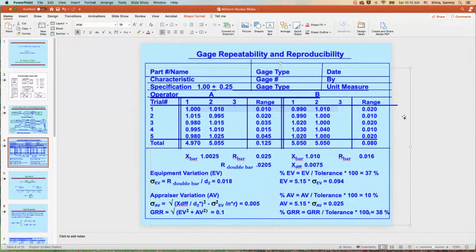And that's tough. And the way that's handled in industry is you take that spec and you reduce it by the error of the measurement, or the error, which includes the part. So if it's 30% and you have a plus or minus 10, you've got to reduce your spec to plus or minus 7, because plus or minus 3 out of that 10 is eaten up by the error in your equipment. So if you ship your product to another company and they do incoming inspection on it and they have a different system, the only way to reconcile these two is to do a GR&R on both sides. And I've been involved in a lot of situations like that, and that's extremely important.